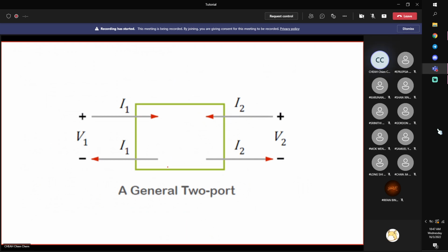Okay, this is a general two-port network as we know, right? You have port 1 with V1, I1, port 2 with V2, I2, and current should flow into it, unless you get a transmission model, then you reverse it, negative I2. But there are special classes of two-port networks like the reciprocal networks. So this is another special class we call the common ground two-port network.